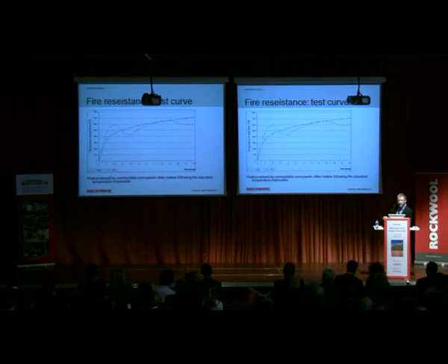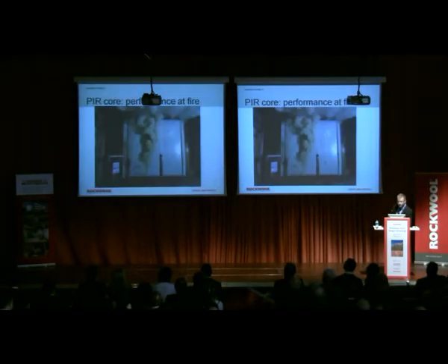The principle of the fire resistance measurement is that you have a testing furnace where you want to create some kind of high temperature curve over time. So this is the standard temperature, the blue one, and the laboratory is trying to simulate or follow this curve. But if you have a lot of combustibles, it is not possible. It is quite common that the burning of the construction itself is so high that you have a very high temperature overshoot, much higher than the standard. It's simply not possible to control.